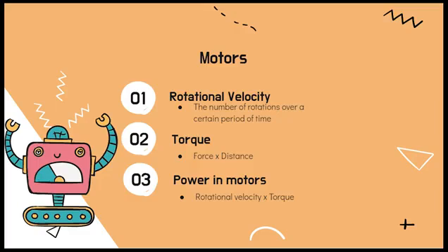The torque of a motor is a measure of strength, since motors provide rotational motion to the robot. As described in previous videos, the torque is the product of the force applied and the distance or length of the arm. Once motors have been designed by engineers, they are most often measured in terms of the power they deliver. In the case of motors, the power is the product of the torque and the rotational velocity, also known as the angular velocity. Now we will provide an analysis of motors through calculations and give recommendations on how to incorporate motors into your lessons for the students.